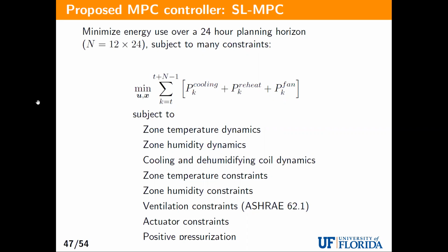Because this was kind of interesting. We discovered it, kind of funny. We should have known about this earlier. We know that buildings typically are positively pressurized, but if you're trying to just minimize energy use, your optimizer might say at some point, if nobody's there, building is completely empty, shut everything down. And that's not good, especially in a climate like Florida, because you don't want infiltration, and moisture might come in, stay in the cracks, cause trouble.